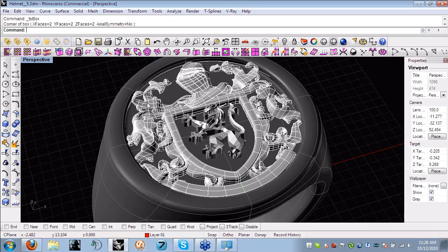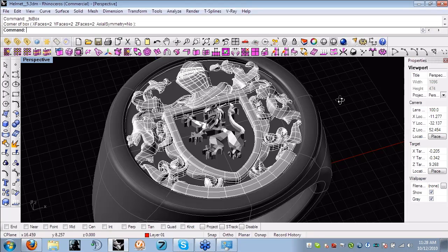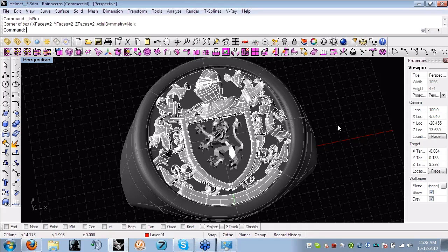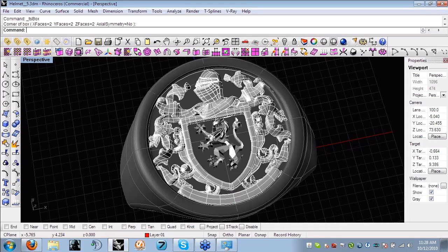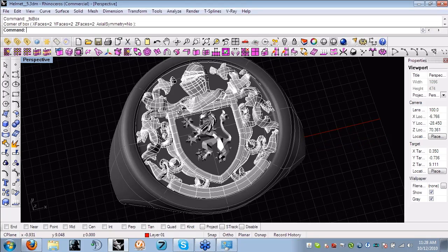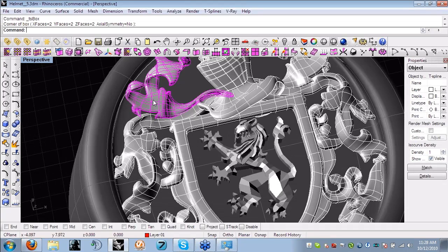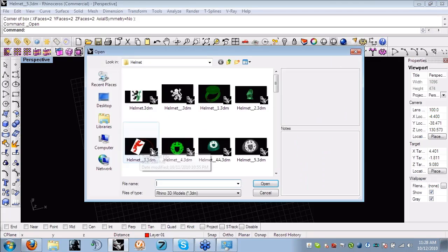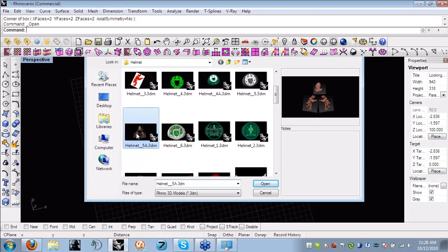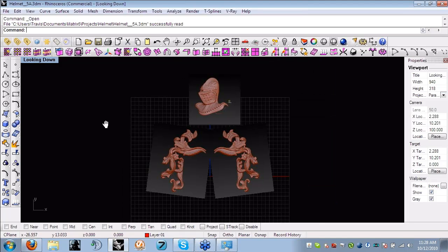And so when we transport over to other applications like ZBrush, the triangles are often too heavy, the topology of the model's not right, and it's just very difficult to get sculpting nice and perfect like you want in ZBrush without having to do a bunch of workarounds. But T-Splines, if we export them in box mode, they will actually come right over into ZBrush and they sculpt up like magic. So this is another huge workflow benefit for us in being able to use T-Splines.